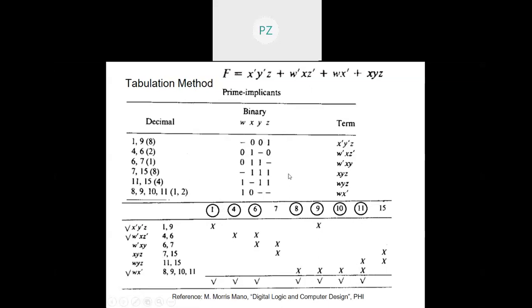So I'll again suggest practice using a case of a don't care. We have taken an example of don't care in one of the earlier lectures, like we did that BCD to 7 segment decoder in the previous lecture. So try designing all the 7 components using the tabulation method now. Or you may also try, out of the 7 segments, 4 segments in sum of product form and 3 segments in product of sum form, using the don't care conditions 10, 11, 12, 13, 14, 15, as we did there. So that will give you a good practice. So we will stop here.